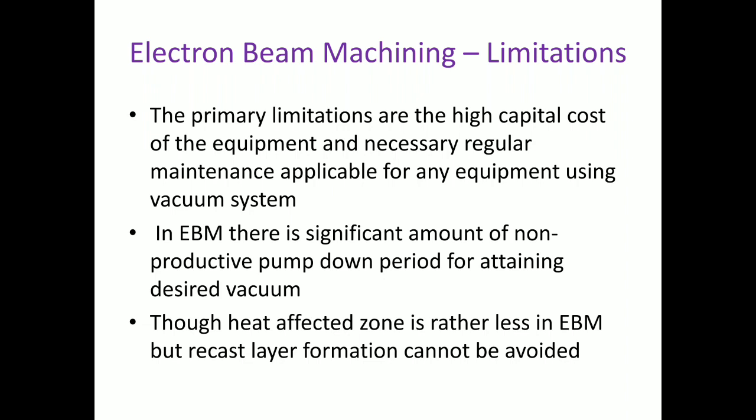The heat affected zone is rather less in EBM, but recast layer formation cannot be avoided. Recast layer is the vaporized material again depositing and solidifying. So this cannot be avoided even though the heat affected zone is small.